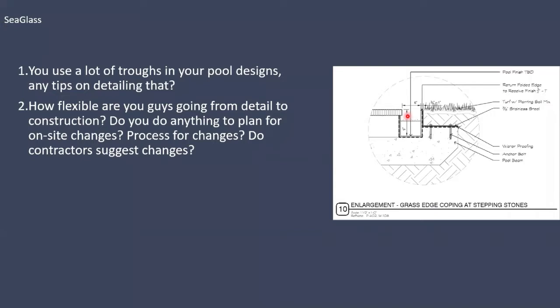And then with the material surfaces we use, even if there isn't a specific slip resistance code, we always want to make sure that people aren't going to slip, especially since the water is always very close. We want to make sure the water is either sloped towards the pool or away from the pool, whichever case applies to them. You still don't want to create any kind of slippery condition outside, whether there's a code for it or not. That's really not good design. Yeah, that makes a lot of sense.